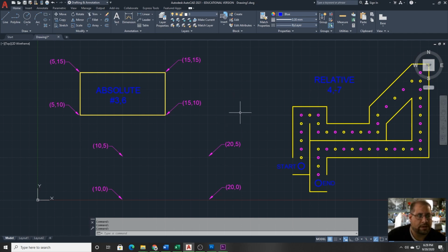Also, you should understand what dynamic input is. Watch as I click this line command. As soon as I click the line command, it says specify first point down at the command bar, but it also says it near the cursor. If you're seeing words and numbers pop up near the cursor and guides and things like that, then you know dynamic input is on. That can be controlled with F12, where I could just turn it off like that. Or it can be controlled by clicking down here on the status bar. Just so you know, that has to do with the way you input things as well.